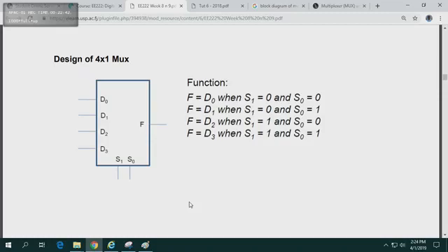So if you were to draw this using a truth table, your truth table will end up with 64 lines, right? If we go back to basics, it becomes very hard, but you can still do it. You can draw a 64-line truth table. From that, you will get your sum of minterms, and from your sum of minterms, you can then put together your Karnaugh map and draw what your function F will look like.